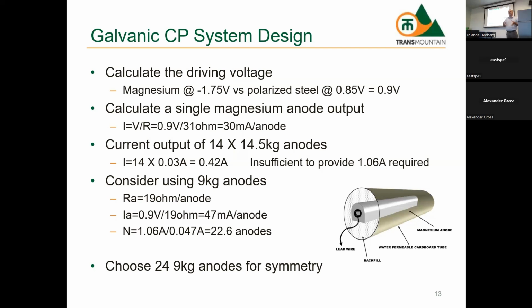That's why you use a conductive carbon backfill in impressed current systems. In galvanic, you want to lower that resistance of the metal to the soil, and to do that, we use this gypsum bentonite mixture to absorb moisture and make it conductive to the soil around it.